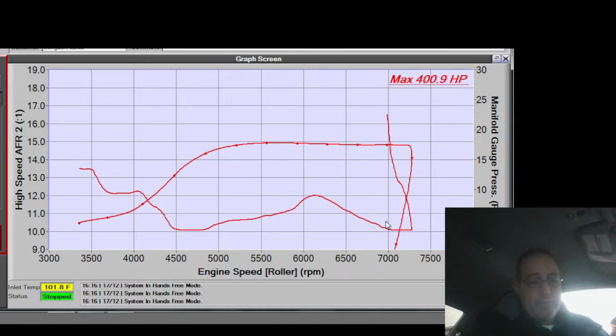With the exception of, once you get too hot, you start to melt the electrode. So you don't want to melt stuff. But that range is pretty wide. You can go pretty hot before you start to melt things. But if you're melting the electrode, that means that your constant heat load is higher than the material in the electrode can handle. That's why iridium and ruthenium came about, because those materials handle more heat before they melt. That's the idea behind those. So that's great, I have a plug that gets hot and it cleans itself.